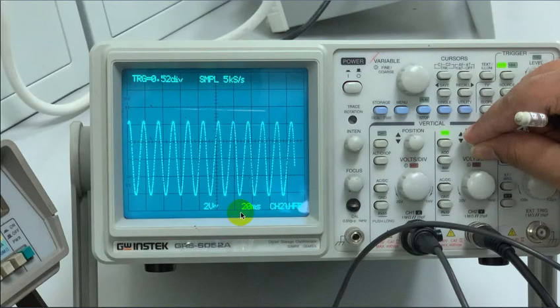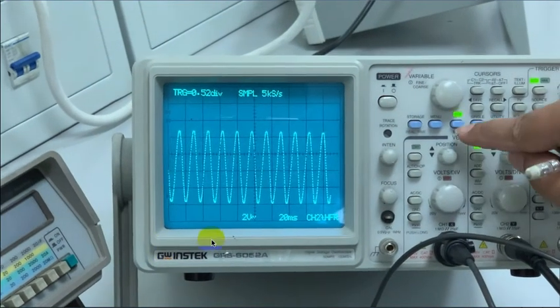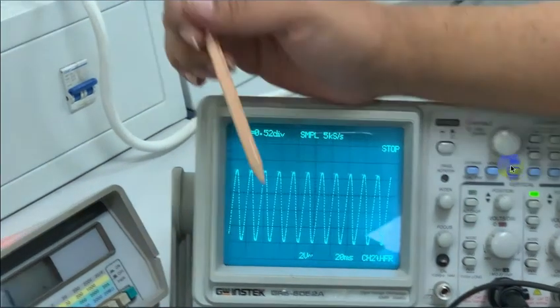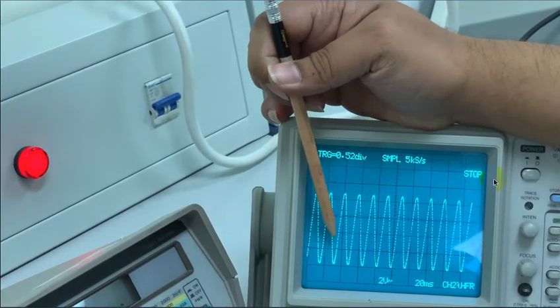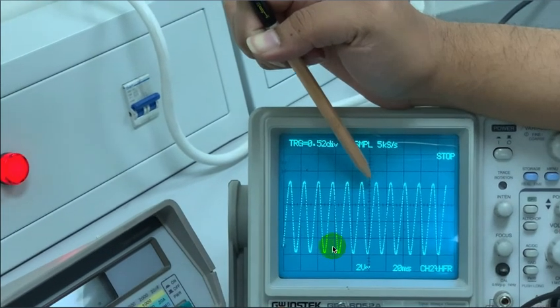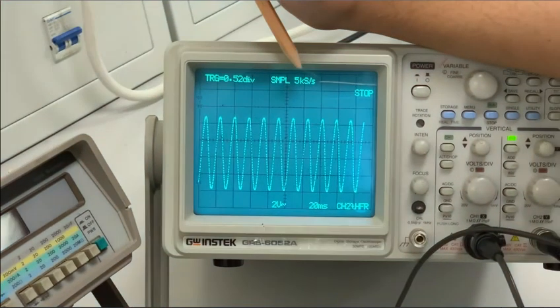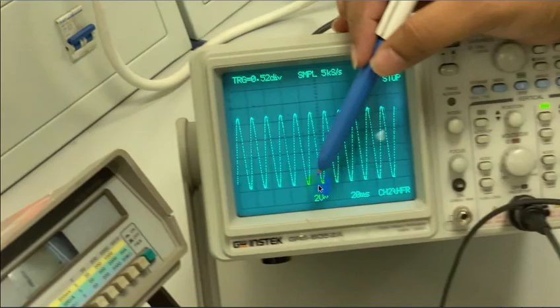you can see, when I stop this, I'm setting it and stopping it here. This button is the run button. So now your waveform is stopped. Now you can count easily. 1 2 3 4, 4.4. You can tabulate the values. This 2 is the deflection coefficient, and this is the height. So when we multiply these two, it will become 8.8.